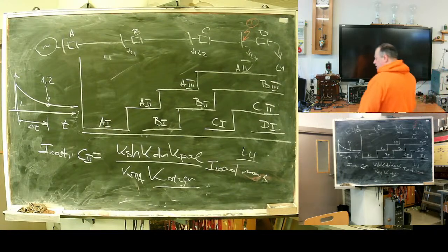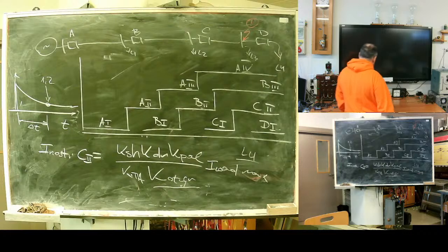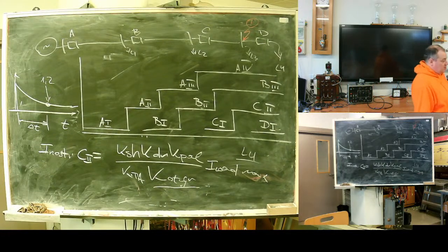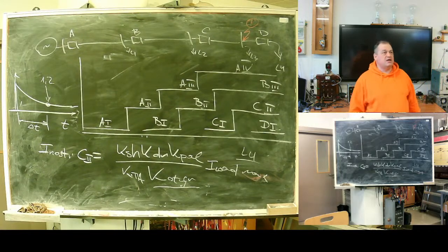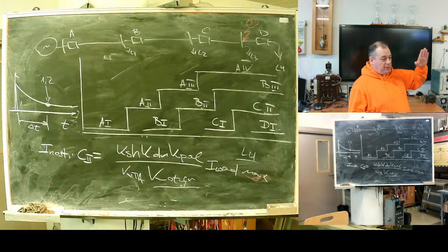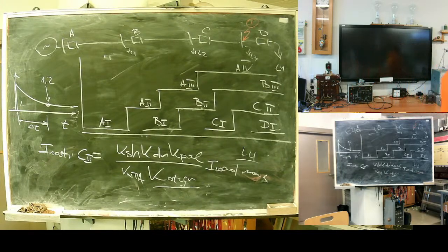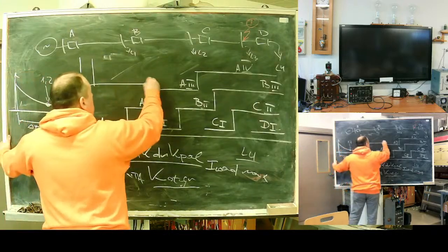For old electromechanical relays, the magnetic resistance of the closed circuit is much smaller than the magnetic resistance of the open one, because the air gap is smaller. That means the current needed to hold the relay in trip position is much smaller than the current needed to move the relay from open position to closed.